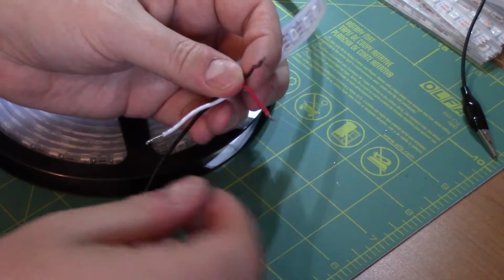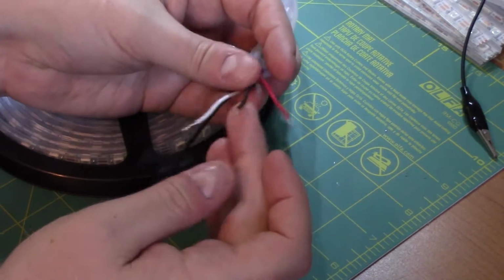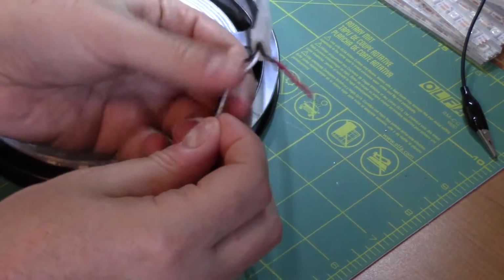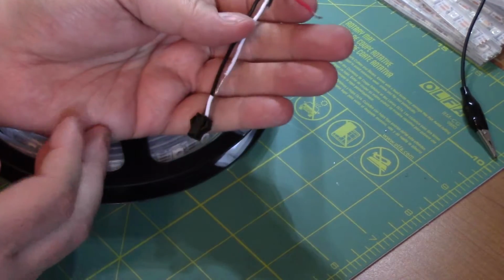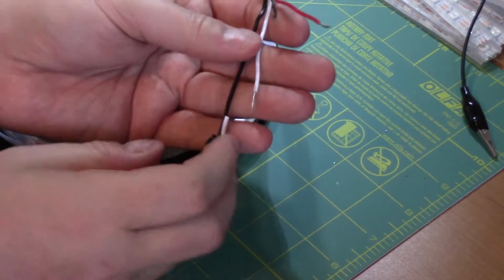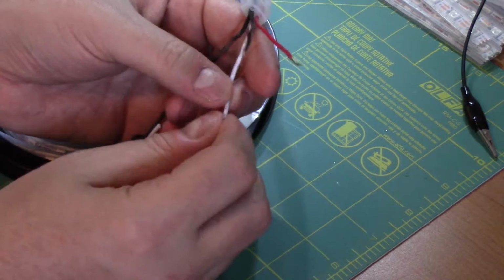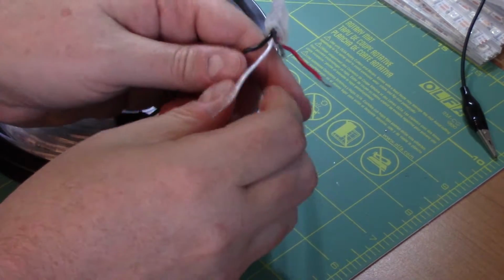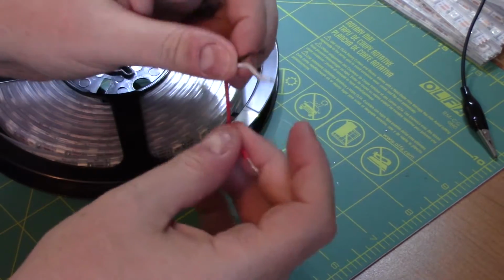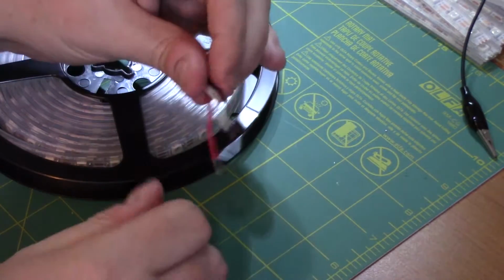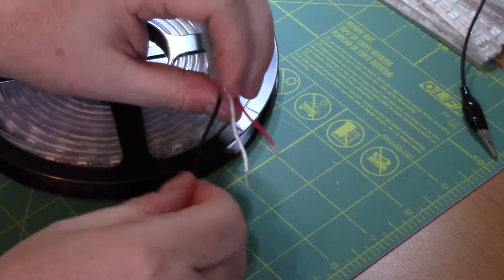It comes with two wires already cut. You've got your power, which is the red, ground, which is the black, and then this one, which I've already chopped up, is a plug with white and black. So that's data and another ground. To get these ready to test, just snip the white wire, strip the end of it, twist it a little bit, and you can fold back that other ground just to get it out of the way. So you're going to end up with three wires: power, data, and ground.